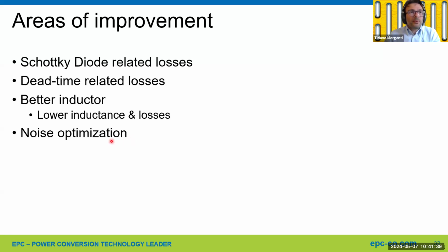So we can use better operational amplifiers and also lower value resistors to reduce the noise in the input stage. And also we can push the feedback loop gain a little bit higher at lower frequency to reduce the noise in the output stage.